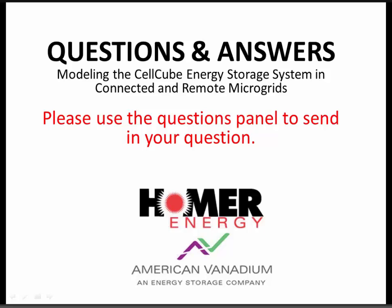Now, that happens to some extent in the vanadium chemistry, but only to a very small amount, because you're not dealing with a chemical change of state in a vanadium redox battery. You're actually dealing with just changing the oxidation level of the vanadium element. Vanadium is a peculiar element. It can exist in 4 valent states, and we use those valent states, 2 on the positive side and 2 on the negative side. So all we're really doing is just changing the oxidation level. So that's the reason we get these very long lifetimes.